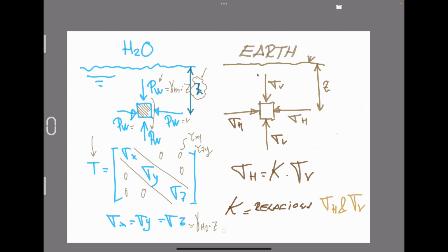Now we are going to generate the same equilibrium forces. Let's concentrate on these differential elements. As you can see, the vertical pressure over this portion of the soil should be the density of the soil multiplied by the depth at which we are creating this balance. Of course, in terms of balance, sigma V is going to be the soil density multiplied by z. But because the soil has a certain shear stress and tangential stress, horizontal pressures don't have the same value as the vertical ones.